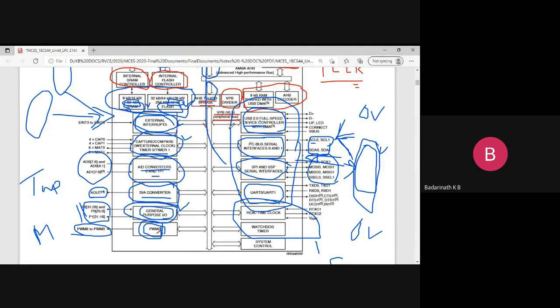In such cases, you have to go for the next version, LPC1768, which provides OTG support, On-The-Go. In the sense, it can act as a device also. It can also act as a host also. So this provides USB device support. So this is also serial in communication. So these are the 4 serial protocols, embedded protocols supported by your microcontroller called LPC2148.